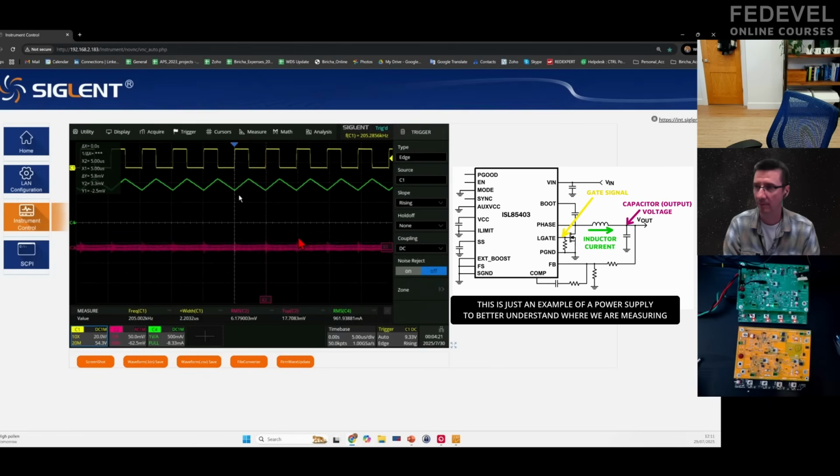And as I said earlier on, the job of the capacitor is to reduce the amount of undershoot or voltage dip. I will demonstrate that in a minute. And reduce this ripple that will go through the capacitor and translate into a ripple voltage on our output. So let me change the trigger so that I can trigger on the current step.